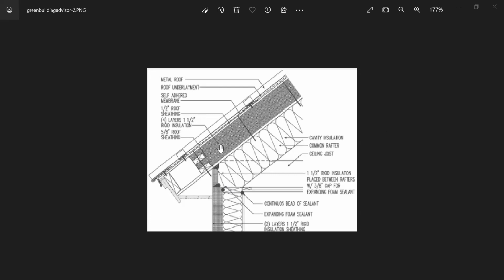We have this very thick layer of rigid insulation. We have a standing seam that shows in elevation. And we have a membrane here. You can see the insulation comes up to meet the underside of the plywood sheathing. We'll have that as well. But anyway, this should just give you an idea of what the detail is going to look like. Also, there is a drip that's here that we'll include in our detail.